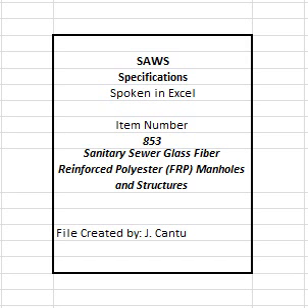Manufacturer's factory location. Manufacturer's serial number. Manhole length. ASTM designation. Installation assist marks, vertical lines 90° apart at base of manhole. 8. Manhole rings and covers, refer to specification item number 852, sanitary sewer manholes for HDPE throat rings and miscellaneous specifications and details associated with ring and cover design and mounting.